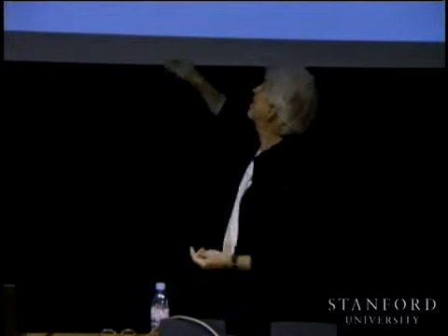X, as you said, minus kp prime x minus x desired. What about the error in velocity? Because now I have x dot desired. What would be the term that I should use to follow x dot desired? So that would be minus kv. Could you finish it? Minus kv. X dot minus x desired dot. Exactly. I form the error x dot minus x dot desired.